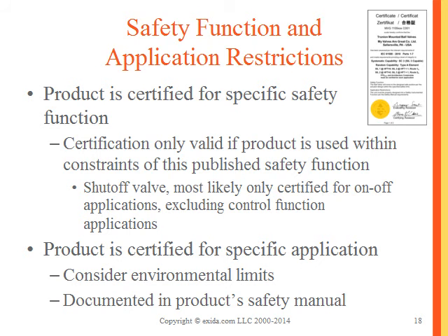If you want to use that valve in a control function application, there's nothing that will say, hey, you cannot use that valve in a control function application, except that the certification at that point is no longer valid. You need to use that product within the safety function as evaluated as part of the certification process. If you use it outside of that safety function, that certification is no longer valid.